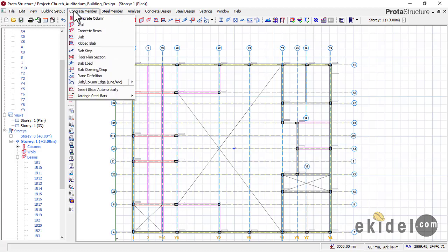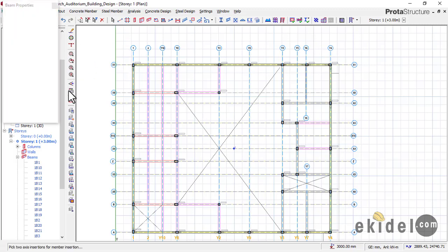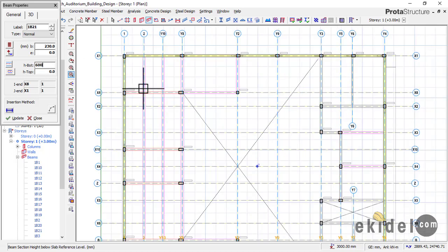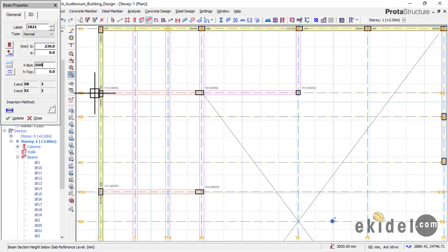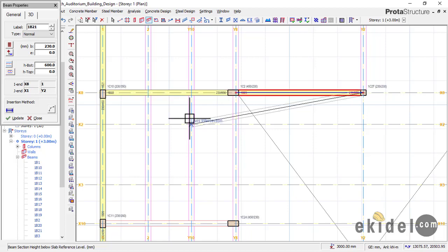Click on the beam on this place here, which is the concrete beam bar, and then go to concrete beams. And then I will go to the place that says beam depth, come here and change my beam depth to 600. Now come here and begin to insert this beam. I'll click on this first point here, and then go all the way down to this place here and then leave it here. Okay.